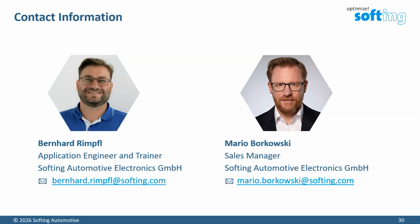And the last question that we think we can answer today: what is the tester address of the Softing DTS tester? Does it follow the SAE standards for diagnostics on CAN, 11-bit or 29-bit CAN identifier, and diagnostics over IP? So can it be classified as a generic scan tool when connected to the OBD port in a real vehicle, or is the Softing DTS tool used only for simulation and bench testing? It can be seen as a generic scan tool.